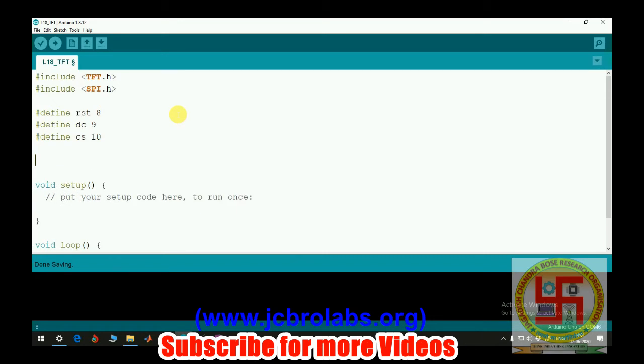Now the next task is to create a TFT object, which will be created like this: TFT, then the name of the object, equals TFT. It needs 3 parameters to be passed. The first parameter is CS, the second is DC, and the third one is RST. These parameters have to be in the same sequence. So this is how we created this TFT object.